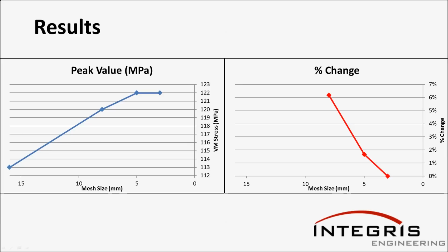So as was seen a few moments ago, there was actually no benefit from going from a 5mm to a 3mm mesh using the color band test, and the convergence on stress shows the same result. Convergence criteria is also subjective, but typical values used are 5% and 3%. And it is going to be dependent on the purpose of the analysis and the analysis goals.